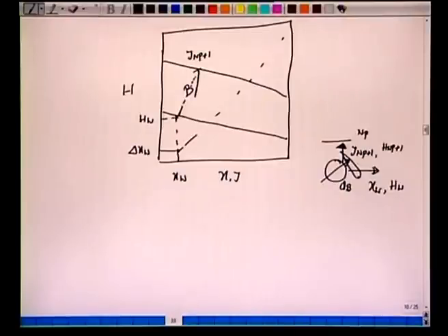Now we can connect this Y Np plus 1 to this X Np. So when we are saying that we are connecting this Y Np plus 1, essentially we are connecting with this X Np. Okay, so this is the liquid composition which comes from the bottom plate Np. So as usual, the definition for this operating line is that now we are connecting Y Np plus 1 with X Np. Okay, now this X Np is in equilibrium with Y Np. So again we draw this tie line to this Y Np.